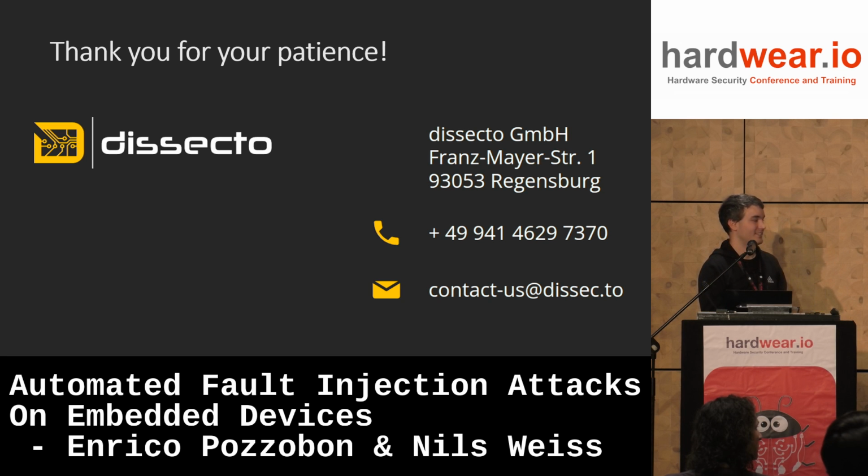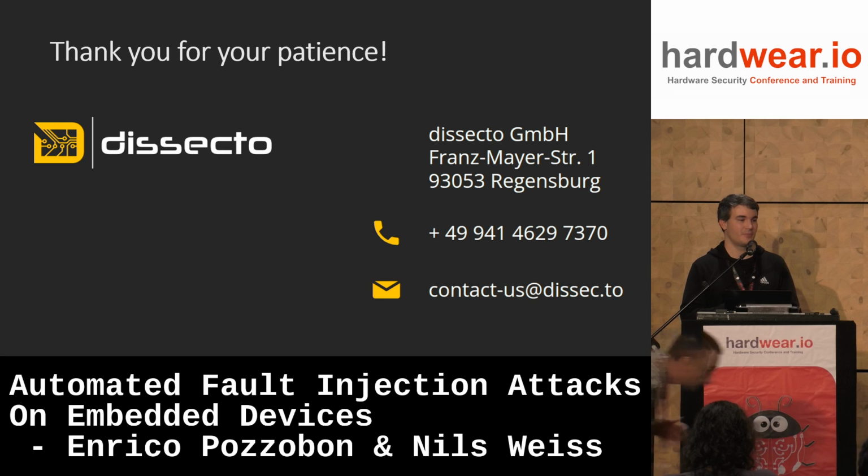So I wasn't clear. You said once you had arbitrary code execution, you could re-enable JTAG. Was that JTAG re-enablement persistent, or was it only for one boot? In the case of this issue that we were attacking, yes, it was persistent, because once we got code execution, we could write to Flash. The Flash has these device configuration files, DCF records. It's a one-time programmable memory, but later records override the previous records.